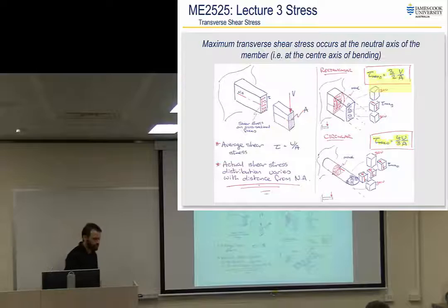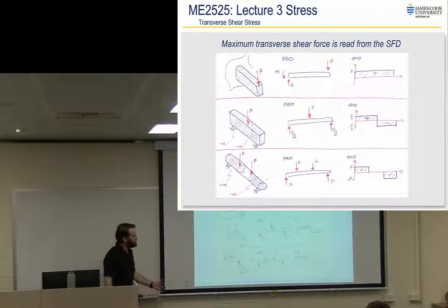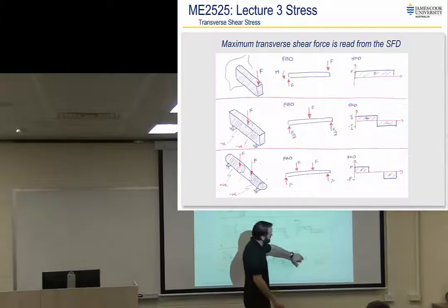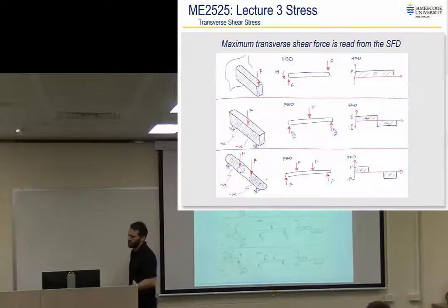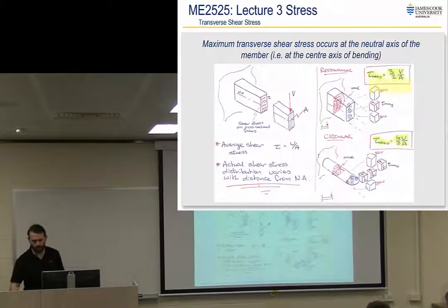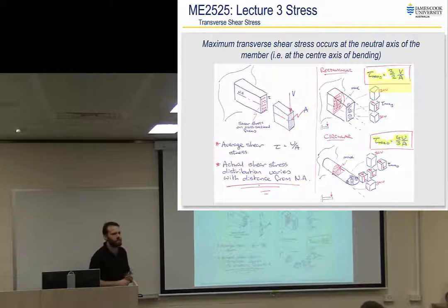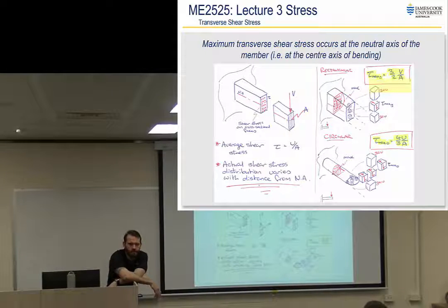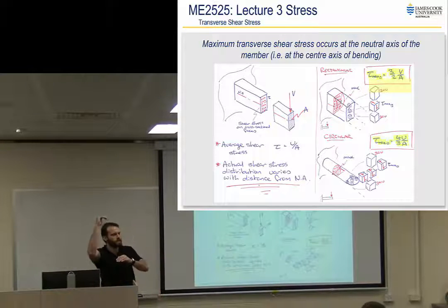All right, so what you're actually calculating on this previous diagram, this V, if I was to just do shear equals V on A, everyone's seen that equation, that's our standard shear equation. That assumes a perfectly even distribution of shear stress. So same at the top section and the bottom and the middle, throughout the entire cross section, even.